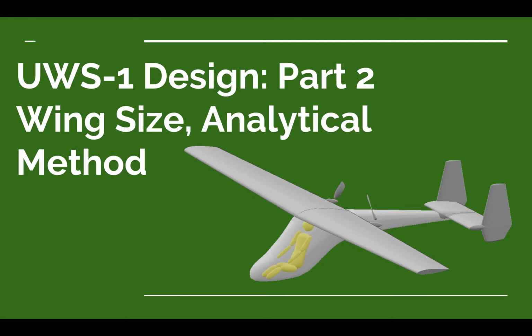Recently, we finished selecting an airfoil for the UWS-1, and now that we have that airfoil, and we've decided to use full-length slotted flaps for the wing, we can figure out what the maximum lift coefficient will be using those slotted flaps and that airfoil, and now we can work backwards to figure out what our surface area for the wing can be. So let's get started.